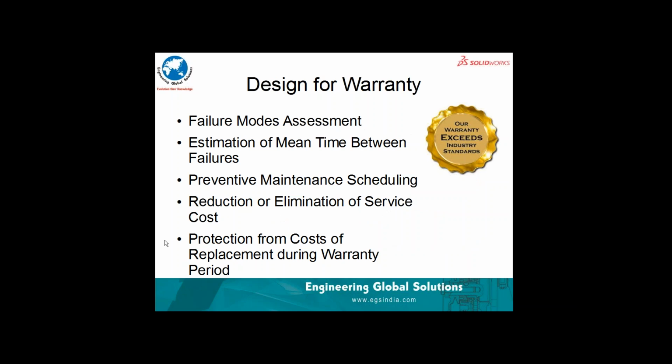Design for warranty is what we need to consider. Here we look at the failure modes assessment, estimate the mean time between failures, schedule the preventive maintenance, and reduce or eliminate the service cost associated with those failures, the bottom portion of the iceberg, protecting from costs of replacement during the warranty period. Imagine the iceberg below the water getting bigger and bigger, eating into the bottom line profitability of the organization. This typically comes from the service calls that we spend from our pocket, that the customer does not necessarily spend when we are in the warranty area.